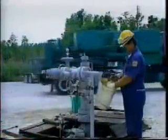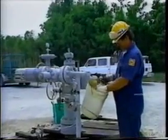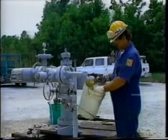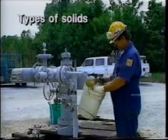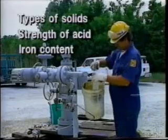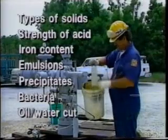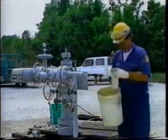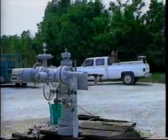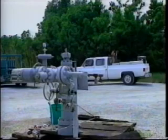It is important to catch samples of the produced treating fluid after the job. Samples should be obtained periodically until approximately 500% of the treating volume is recovered. The fluid should be tested for types of solids, including amounts and sizes, the strength of the acid, iron content, emulsions, precipitates, bacteria, and approximate oil-water cut. The flowback after the treatment should be restricted, especially for sandstone wells. Excessive drawdown can result in the plugging of the formation by fines and precipitates.